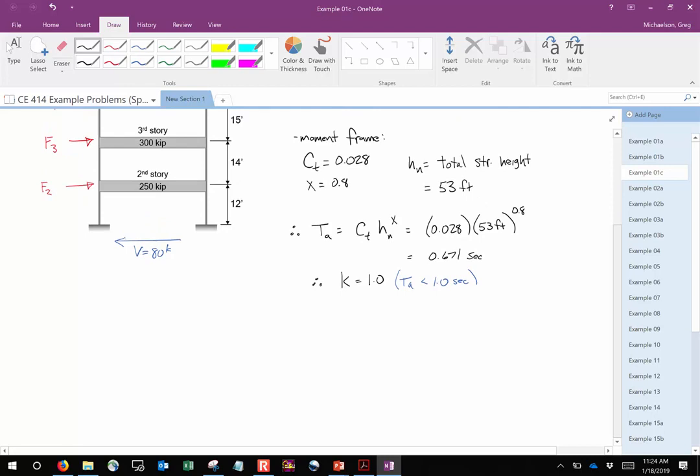All right. Are there any questions on this? Okay. Yes. That's a good question, and the answer is no. When we determine effective seismic weights, we are looking at, for the most part, self-weights. But, great question. All right. Sound good? Okay.